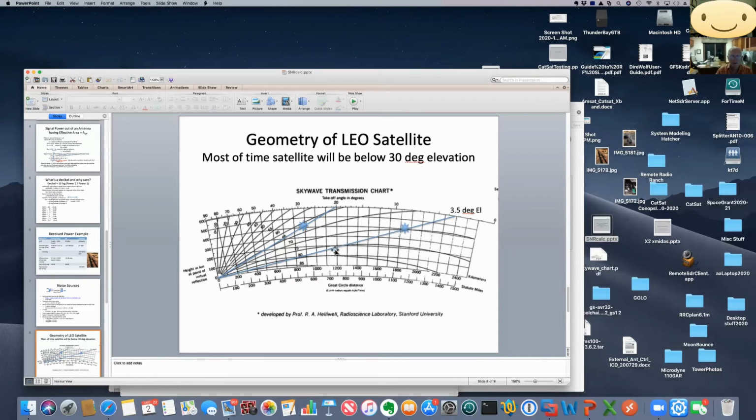I'm not really going to see the signal at this frequency if it's below the horizon. If I bring that down to a curved Earth, it's about 1,900 kilometers. As a straight line, it's going to be about 2,000 kilometers. So these distance figures take into account the fact that the Earth's curving.